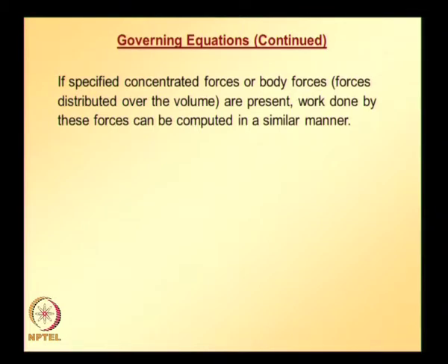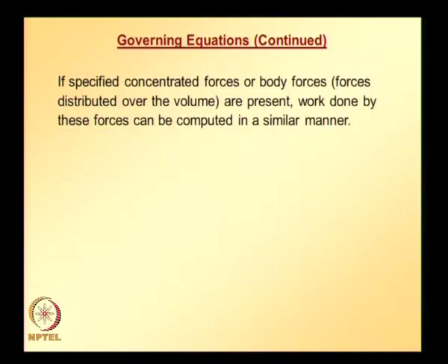So this is what we have seen in the last class, and also in last class we have seen how to calculate principal stresses once we solve for the displacements and find strains and stresses at the points that we are interested, and later using the 6 stress components, we can calculate principal stresses for subsequent use in the failure criteria. So, with that let us start deriving finite element equations for 8 node hexahedral or brick element.